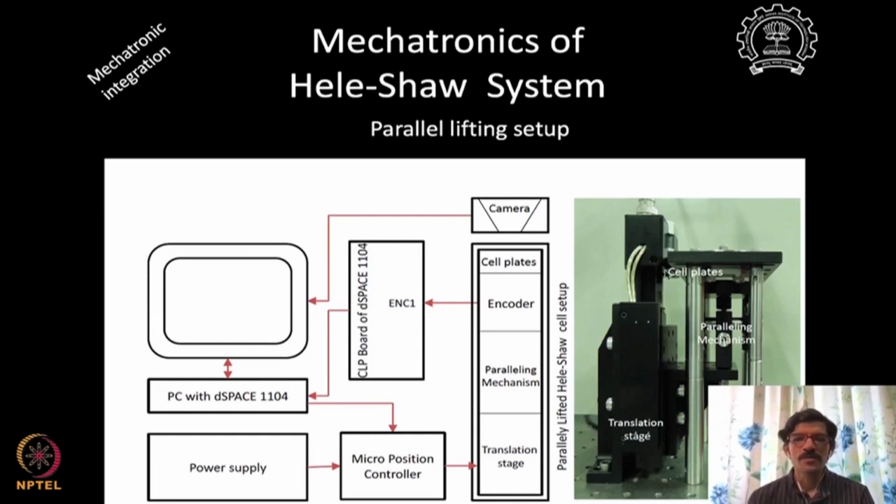So that's why I said we can have the actuator as the voice coil actuator, or we can use these stepper motor actuators also. Here there are ball bearings to guide this in the vertical direction, and the stepper motor to actuate. So a lot of friction exists in the system, but that is overcome by the stepper torque, and even then we are able to move in small steps at a very slow speed.